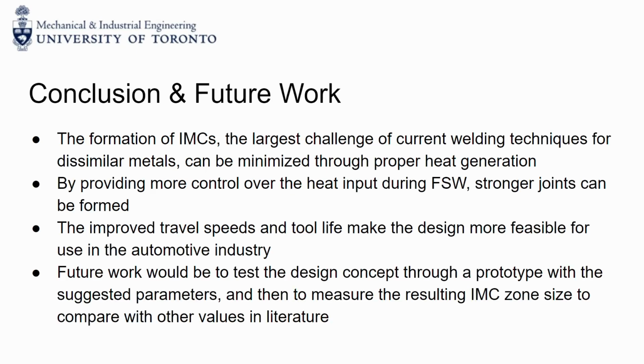To summarize, the formation of intermetallic compounds is the largest challenge for current welding techniques to join dissimilar metals. And the IMC layer size can be minimized by controlling the amount of heat input to the weld. And we propose doing this by adding a supplemental heat source through the use of lasers. At the same time, the additional heat source allows for improved travel speeds and tool life due to the lower forces involved, which makes the process more feasible for use in the automobile industry.